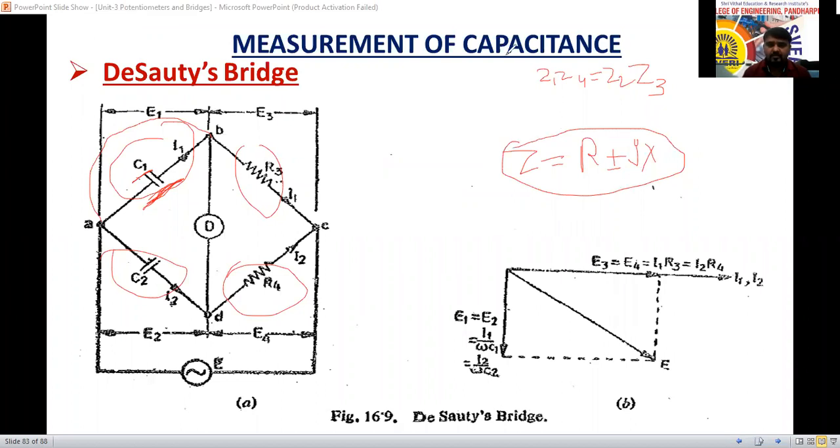Listen carefully. You have to reply, keep replying. For inductance bridges, Maxwell bridge, Hay bridge, Anderson bridge, DeSauty bridge, Schering bridge, you have to remember this formula Z1, Z4 equal to Z2, Z3. And for the Wheatstone bridge and Kelvin double bridge, you have to remember only R1, R4 equal to R2, R3. Later writing the value of R1, R2 is easy; writing the values of Z1, Z2, Z3, Z4 is a little bit difficult for you people.